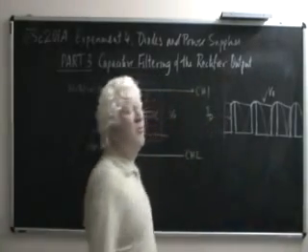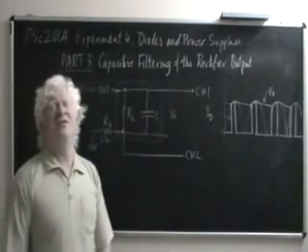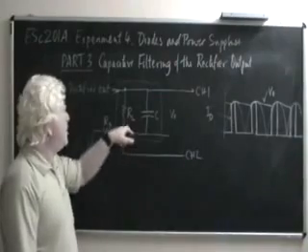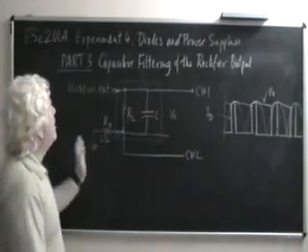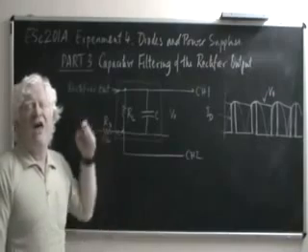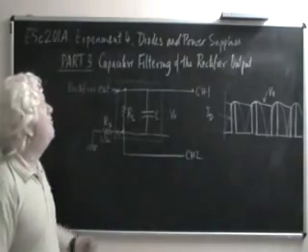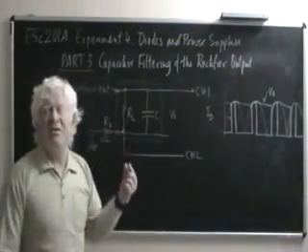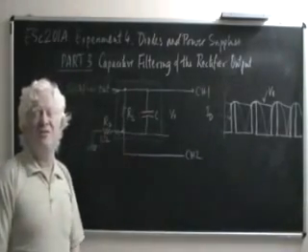The diode current waveform would look like this. The diode indeed has to pass a reasonably large amount of current to maintain even a moderate amount of current in the load resistor for the entire cycle, because all the current that flows through the load resistor over the entire cycle has to be supplied in terms of an equivalent amount of charge over a very, very small fraction of that interval. And that fraction gets smaller and smaller as the capacitance gets larger and larger.